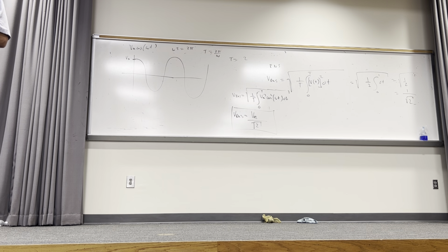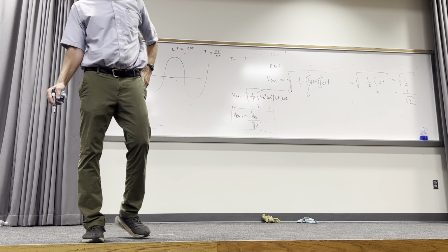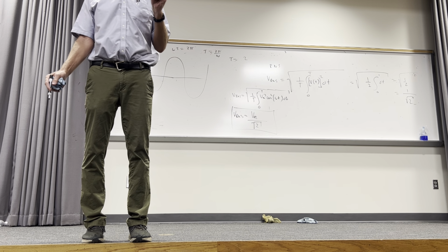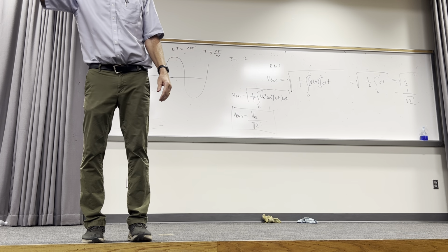And when you look at the actual wall voltage there, what is it about? Do you remember? Anybody? It's called an RMS value, right? How many know it's about 117 to 120, depending on the book you use? Well, that is not the peak value. That is the RMS value. You'd have to multiply that by the square root of 2. It comes to about 170 volts for the peak. That's the actual peak value. Just so you know that.